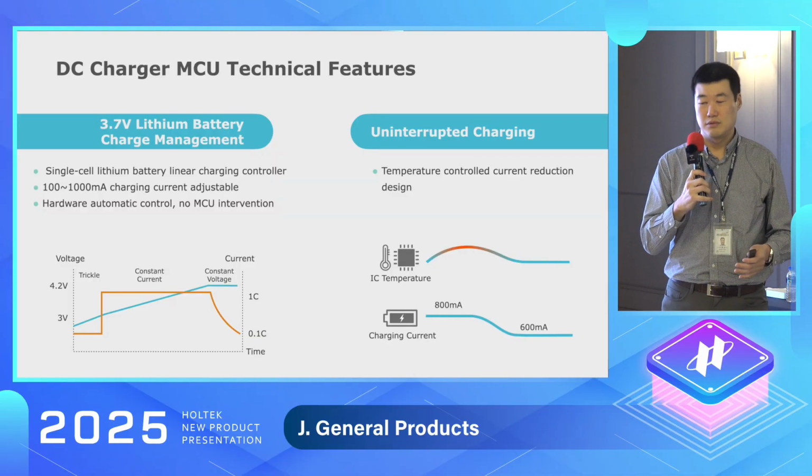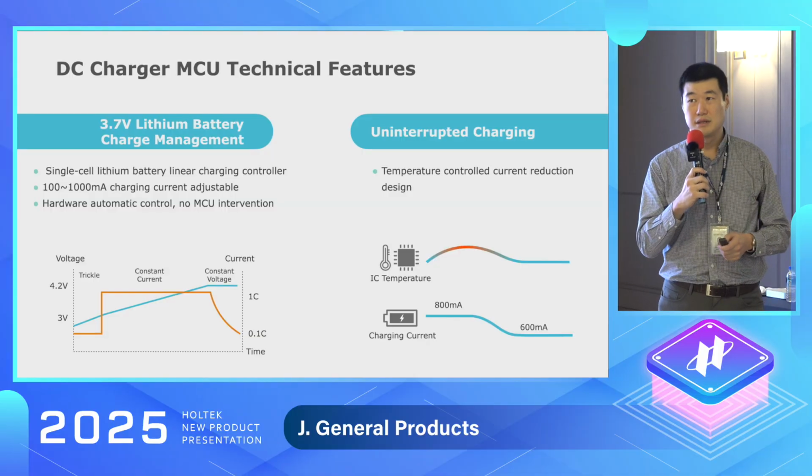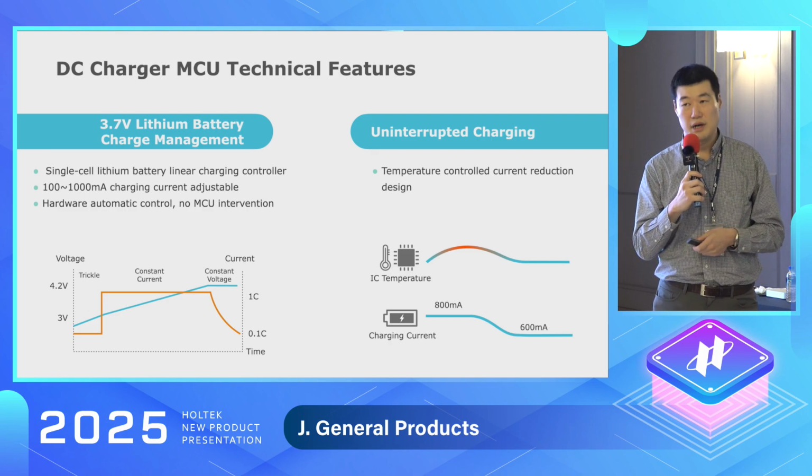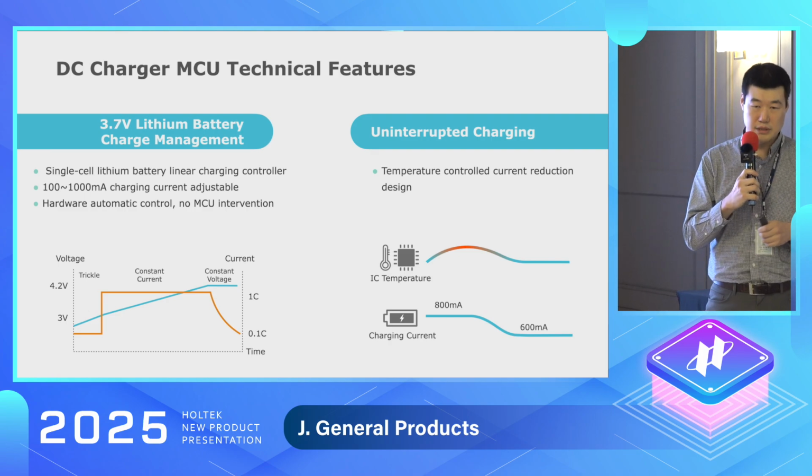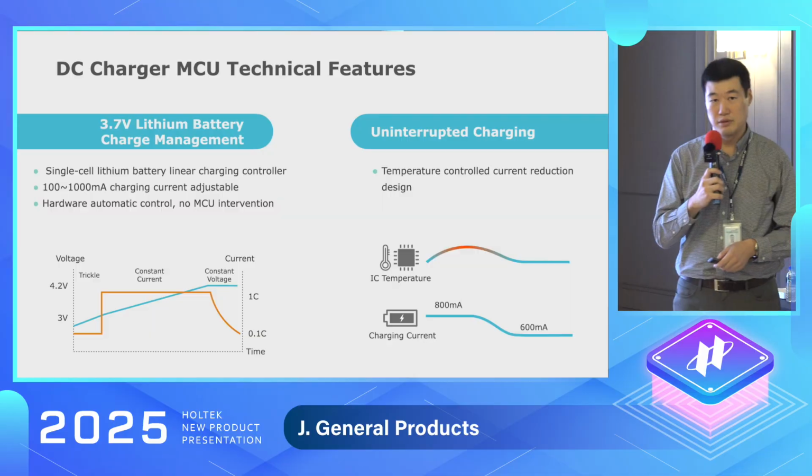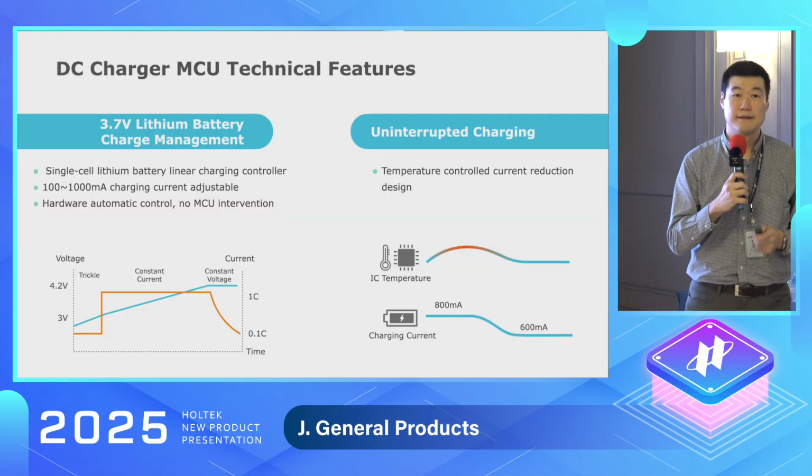On the right-hand side, you can see the temperature controller built in. When it detects the IC temperature is going up, we automatically lower the charging current. So it's also for safety reasons.